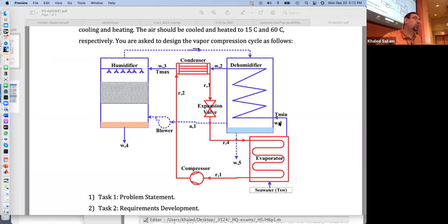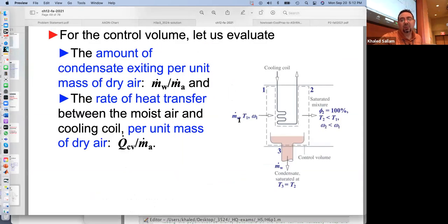From the continuity equation, yes, the water coming here will split into two ways, 4 and 5. But notice that this W1, as we're going to see today in homework problem number 1, that flow rate is not just pure water. It's m dot water plus m dot salt, and the m dot salt will leave intact. It's the m dot water that gets reduced or split. So incoming here is not just m dot water; it's m dot water plus m dot salt. We will see it in the homework.